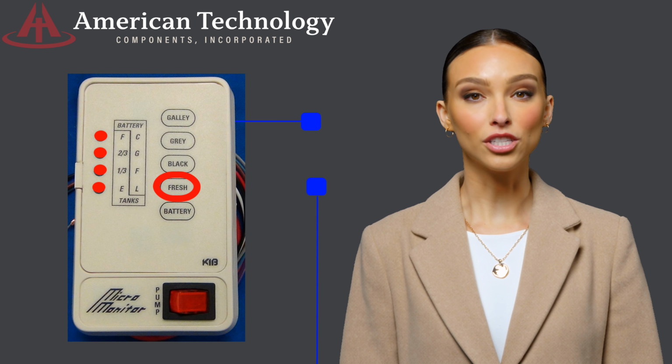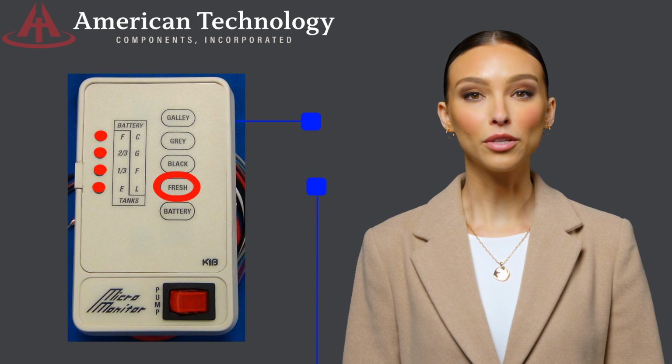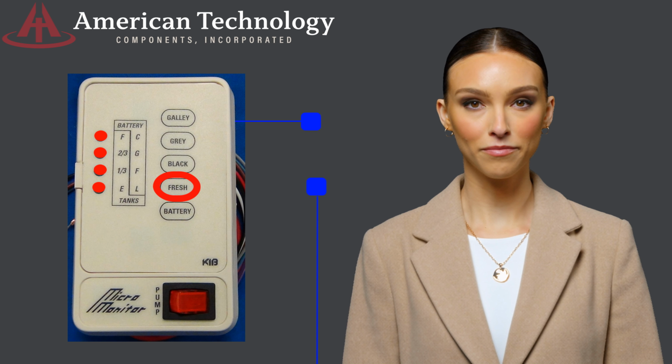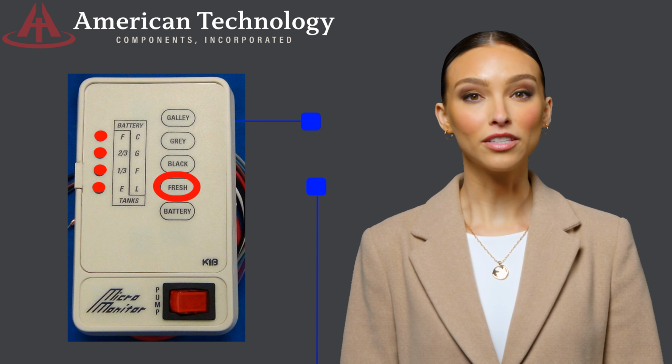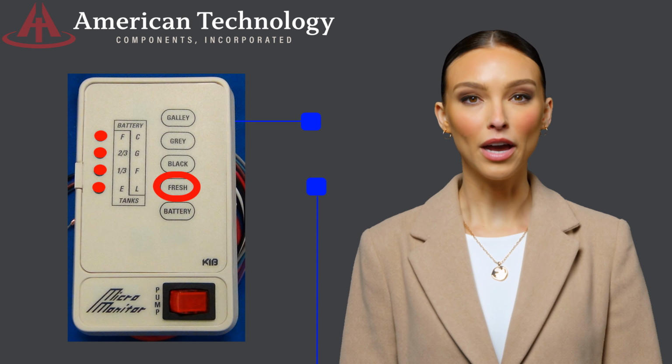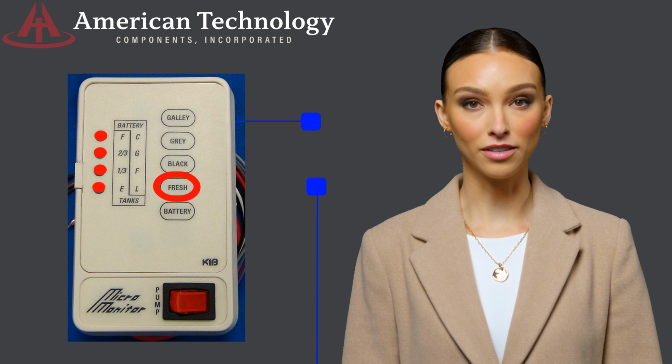If these two actions produce the response as indicated in this section, your circuit board is operating as designed and your issue is within your vehicle harness. If you do not get the response as described, the board has failed and should be replaced. You can contact your vehicle manufacturer or dealer for replacement parts.